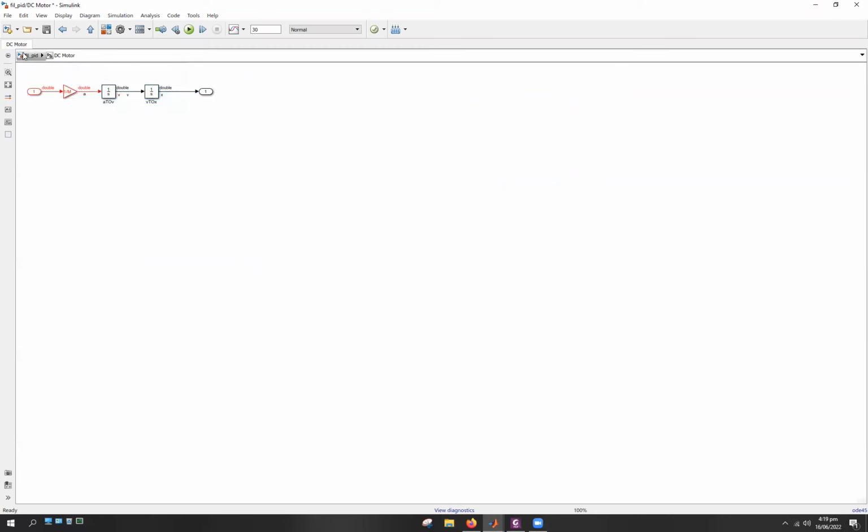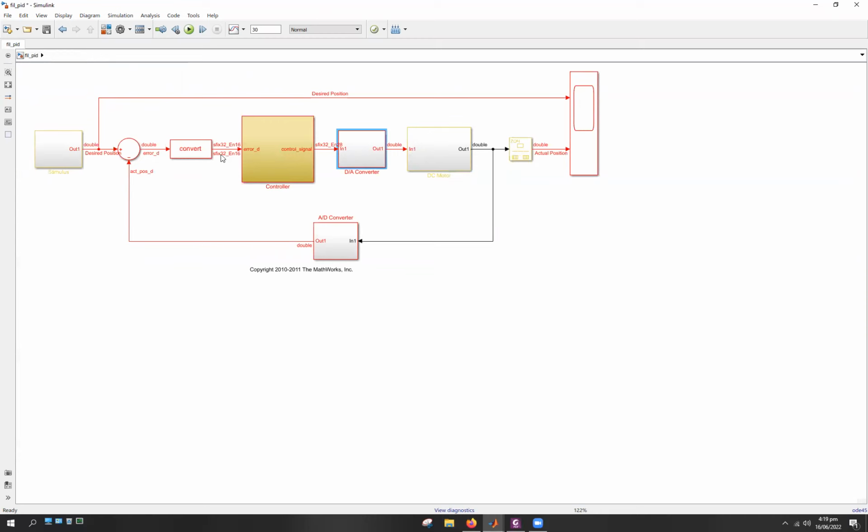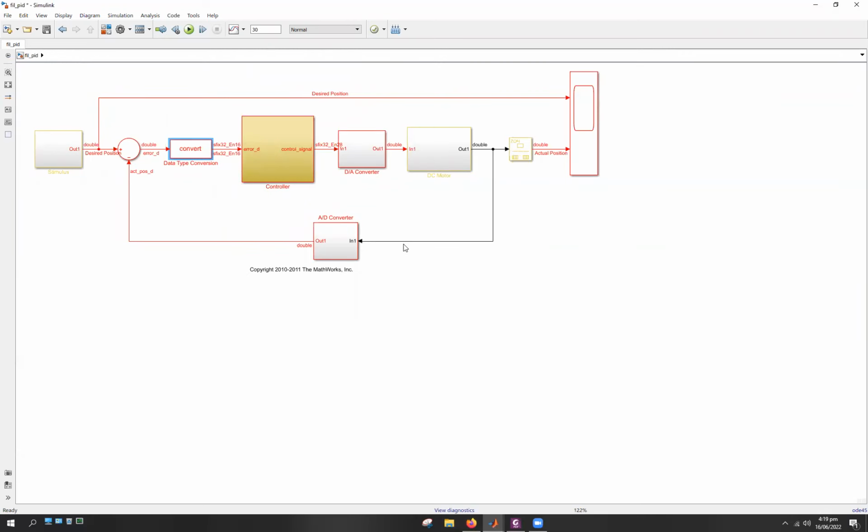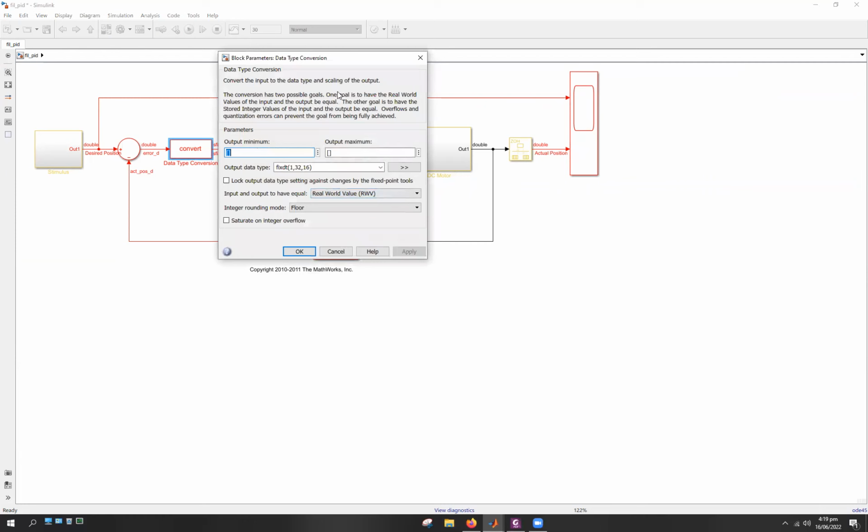and then we have these digital to analog converters and the data type conversion blocks in order to achieve compatible data transition between the FPGA and the simulation environment, because the FPGA is a digital device, so the data that has to be transmitted is also supposed to be digital, and for that we need to convert our data type. For example, regardless of what your simulation environment is working on, the JTAG interface that is provided by the FPGA with the simulation environment is only 4 byte or 32 bit wide, so we have to ensure that the appropriate data conversion type is also used.